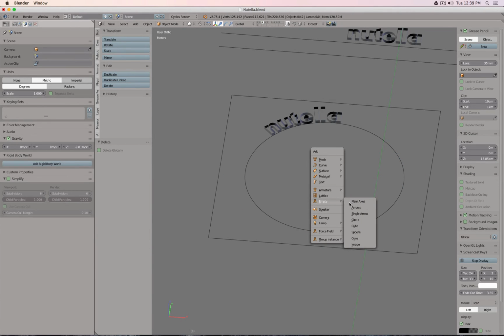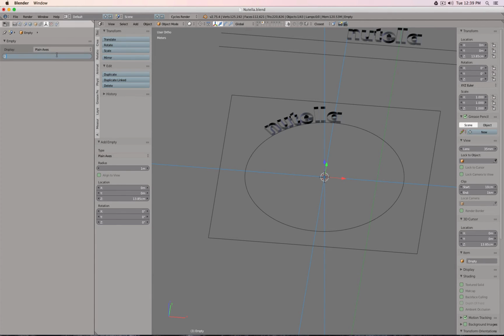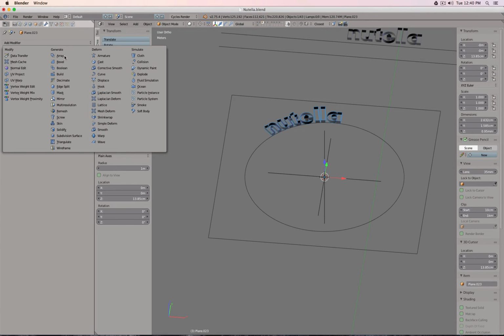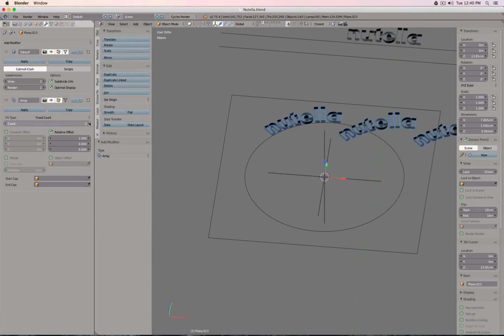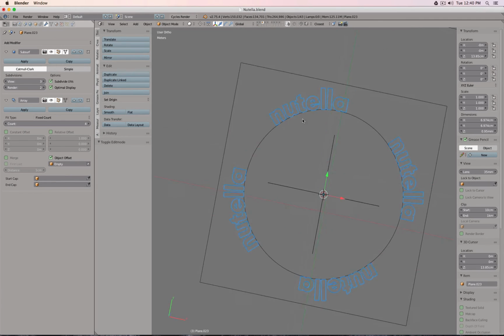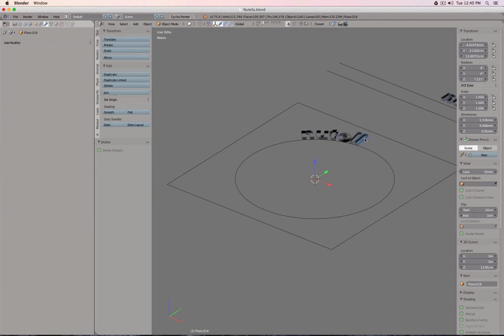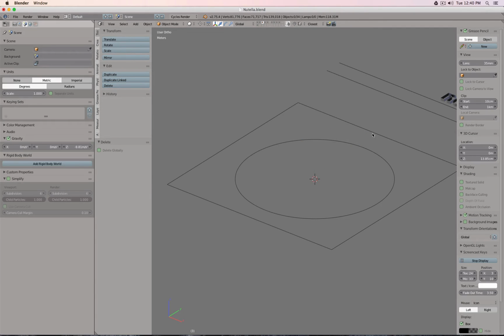So let's make a simple axis. For example, scale this one down to centimeters. Okay, 360 divided by 4, which is 90. So, and then U, array modifier, 4 steps, no relative, offset this empty, and there we are. Zip, perfect. Okay, so let me delete this, because I have this already pre-built, but this is basically the way